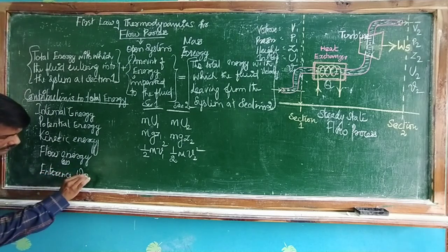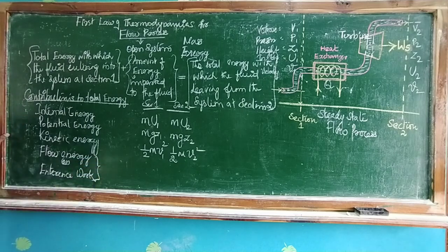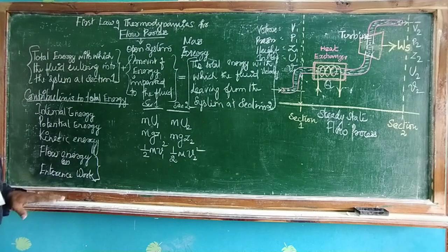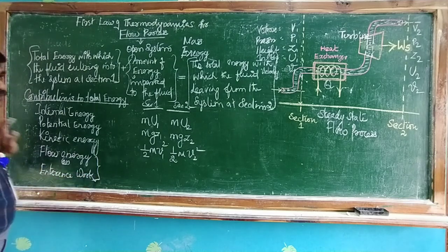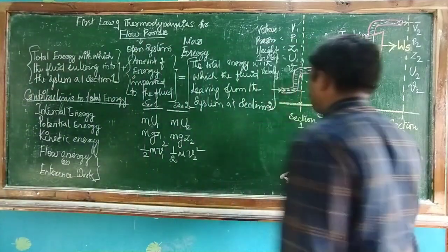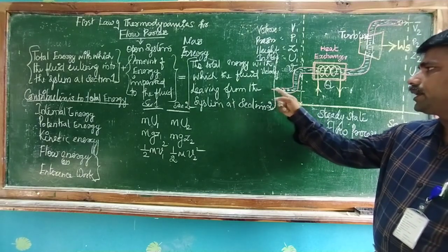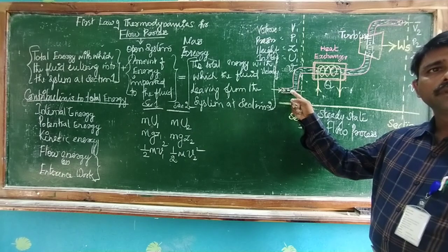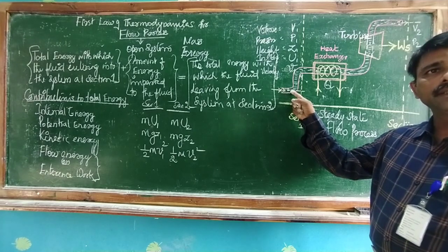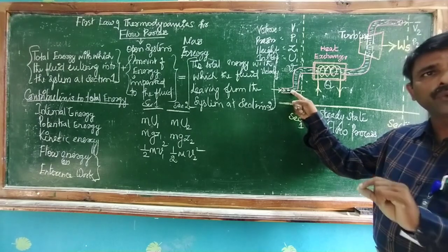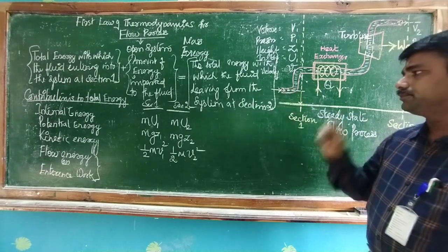Entrance work. Both are the same. Some textbooks use flow energy, and some use entrance work. This means a fluid entering into section 1, a fluid entering into the system, is being pushed by the fluid behind it.